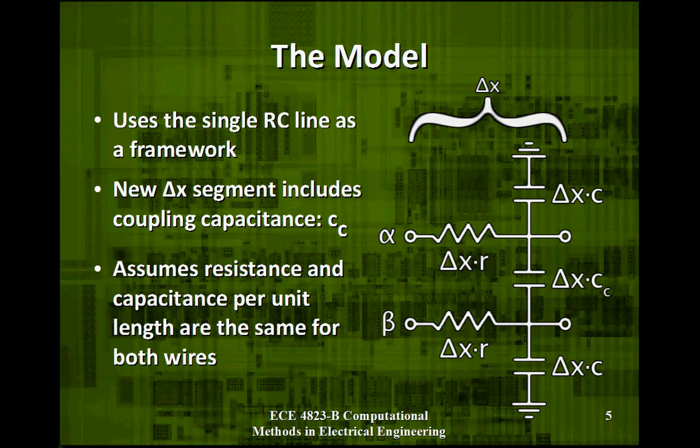Now there are a few assumptions made here, namely, the two wires are identical. For a more general model, R and C for each wire could be different. Because I am merely taking a qualitative approach to the issue of crosstalk, I believe this assumption is an acceptable simplification. To get the equations from this model, we solve KVL and KCL for a segment of both wires.